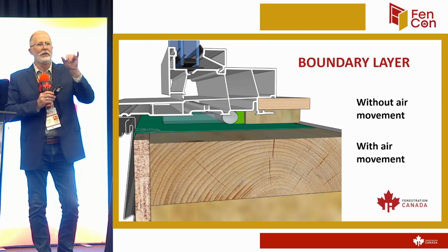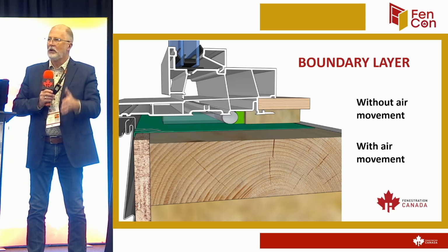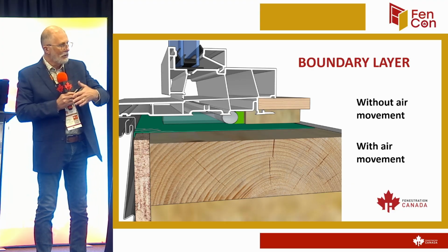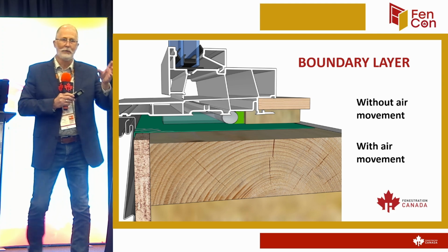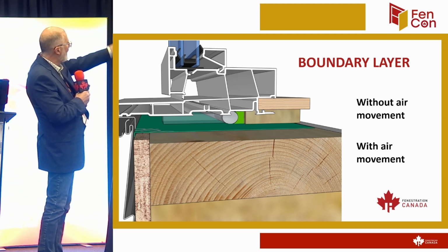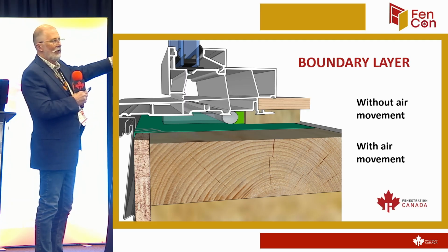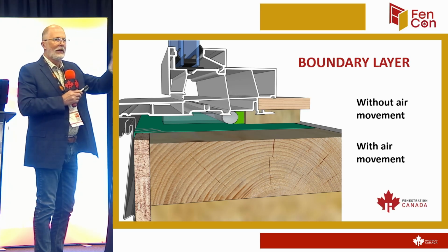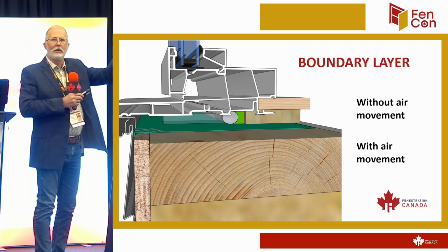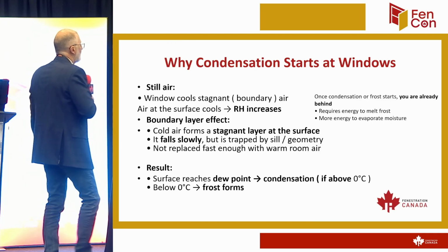If you think of insulation in the wall, and you think about where the wall sheathing is, don't you try and put more insulation outboard than you do inboard if you want to reduce your problems with the sheathing getting wet? So look at the amount of plastic on the outside of that glazing point to the inside of that glazing point, right? That window is going to be much warmer than if you split that 50-50, or if you have all your empty spaces on the exterior and hardly any on the interior. So the design of the window could make a big difference too.